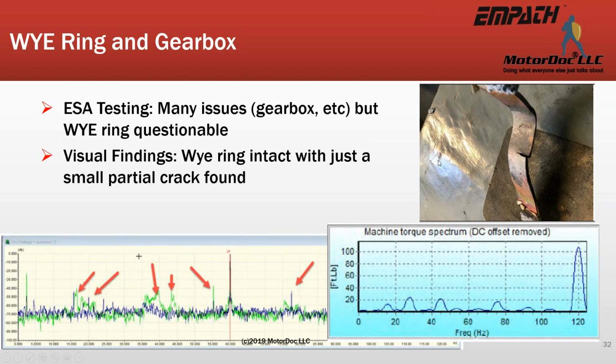Well, how can that be? So they said, well, what was your theory? And I said, very simple. If I have a resistive or impedance unbalance in the circuit, it causes a change in the magnetic fields in the rotor, causing a bulge. So I end up with 2 conditions. One looks like a broken rotor bar, which is pole pass frequency, and the other one is dynamic eccentricity, meaning that I'm magnetically orbiting. The rotor may be dead center in the generator, but it's magnetically orbiting inside the stator.